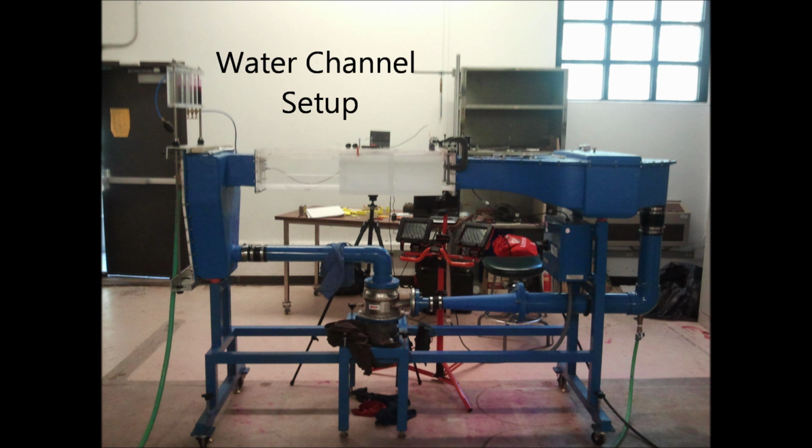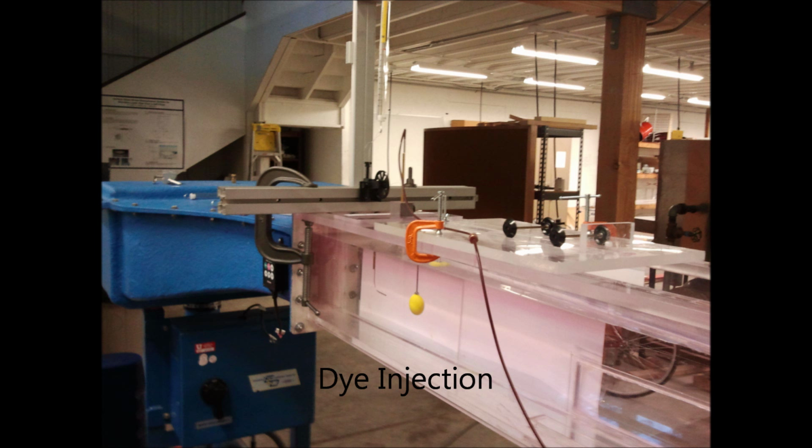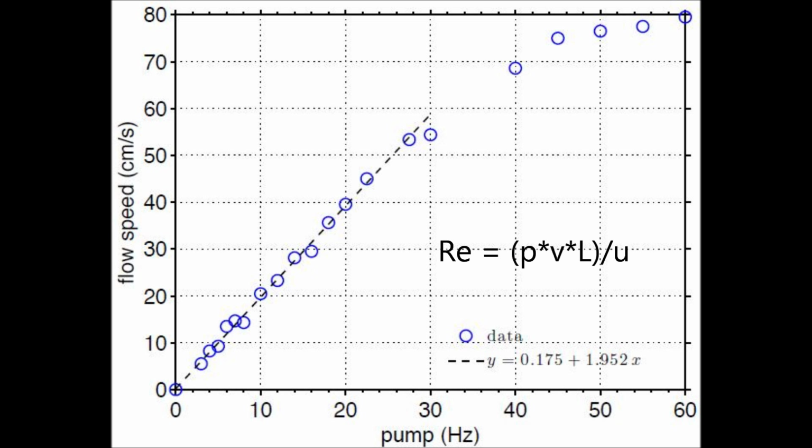To examine this behavior, a model golf ball was fixed inside of a water channel with adequate dimensions such that wall drag could be neglected. A pump was used to alter flow velocity, and a dye injection needle along with a high-speed camera was used to observe the unsteady streak lines. To correlate pump frequency to Reynolds number values, this calibration chart was used in conjunction with the given equation.